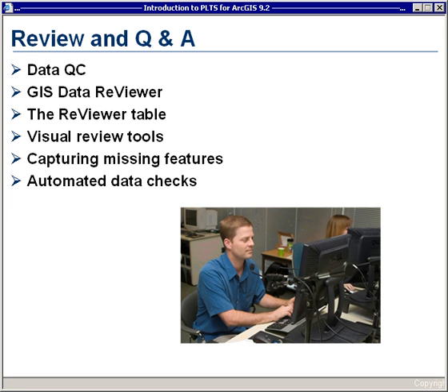Last question from Denise from the town of Basalt. What is the advantage of PLTS over ArcEditor? So I guess the answer to that question is the whole purpose of this presentation. But in particular, with regard to editing, PLTS provides you with some additional validation capabilities. The standard ArcEditor geodatabase functionality allows you to set up domains and subtypes, and you can set up database topology. I like to think of it as concentric circles.